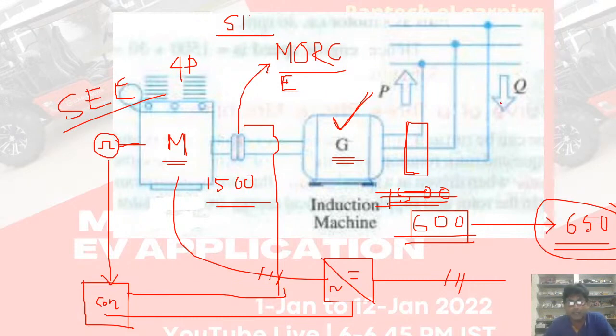Now the first thing in the sequence of operation is you de-engage the clutch, to start the motor which will be working as a generator.